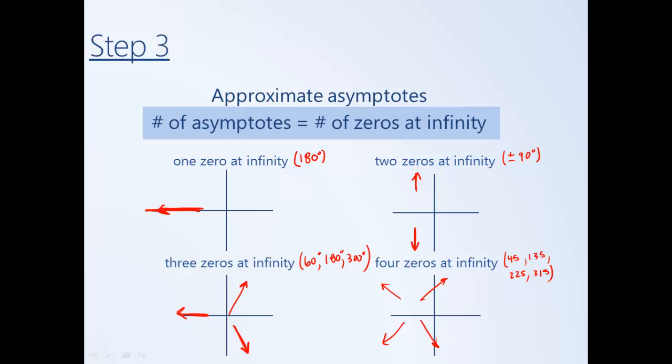What we won't solve for by hand, however, is the exact location of the asymptotes. So we'll know their directions but not their locations. We won't know where the asymptotes intersect the real axis. So technically we won't know if the asymptotes intersect in the left half plane, or in the right half plane, or if they are centered at -1, or if they're centered at +5. That we won't know. There is a way to calculate that. You can find it in your book, but for our purposes we're happy to just get a rough sketch of the root locus.